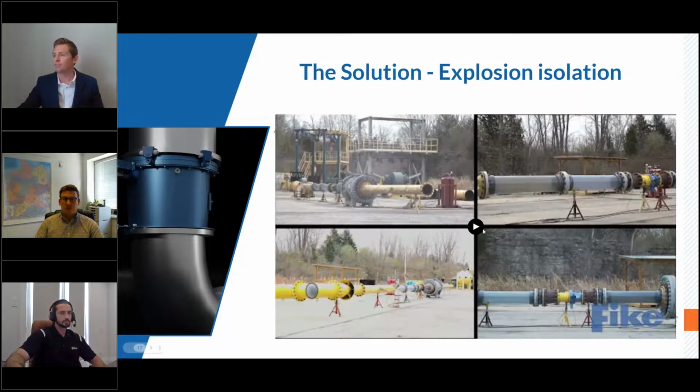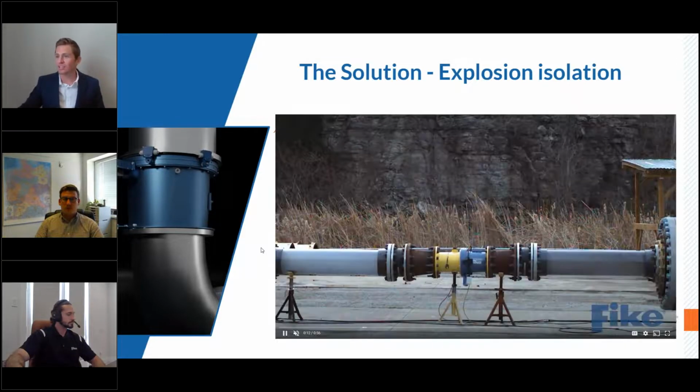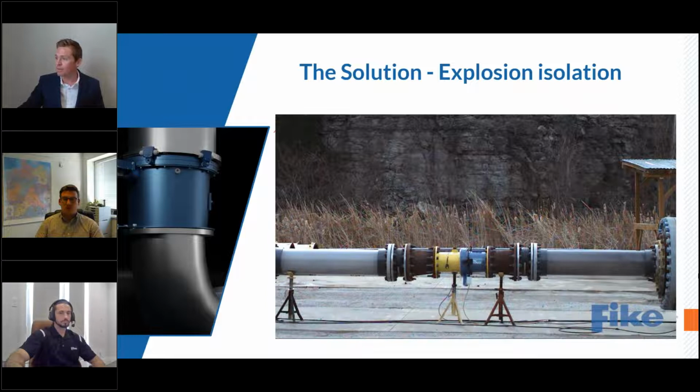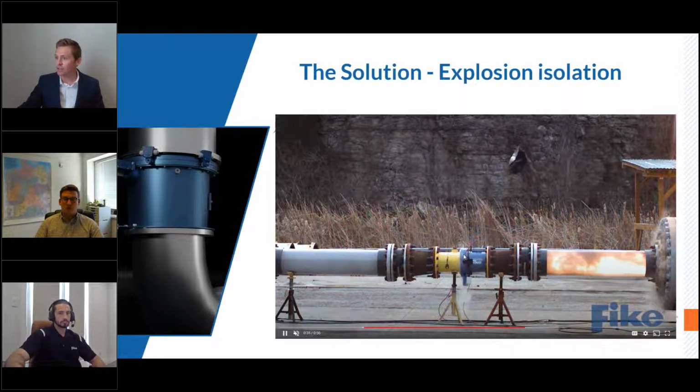Here's a quick demonstration. This is at our remote test site. This is cool because you can see Lexan pipe. So here's the dust being conveyed into the enclosure. You can see it's still moving. It's still moving. And then it ignites. And then when it ignites, it travels back upstream. And this explosion isolation valve is slammed shut. Here comes the pressure wave. Boom. It's slammed shut. You can see it there.